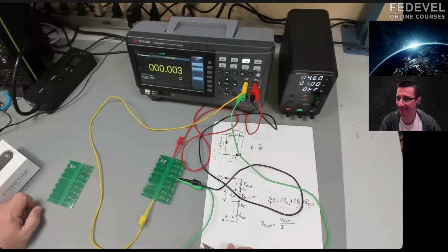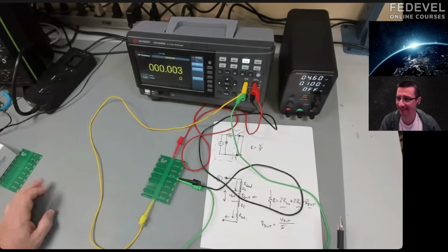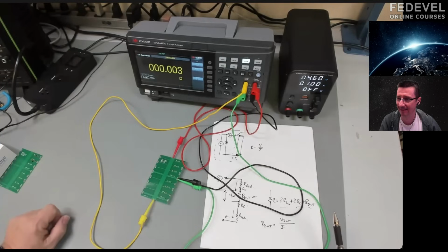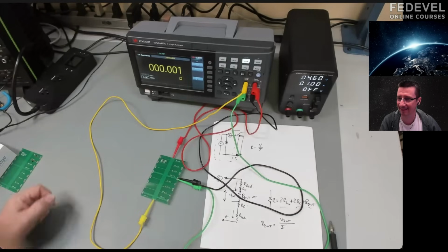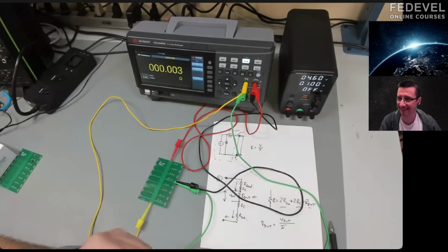So I'm going to show you another technique that's going to let us measure really low resistances. This is a method we use; I taught sophomore circuits last year, and they do take-home labs, and this is a lab that they did where they actually measured the resistance of a 22 gauge wire. It's like 15 milliohms per foot, and they were able to measure it really easily in their home dorm rooms with their little kits. So it's a really simple method. And here's what we're going to do.